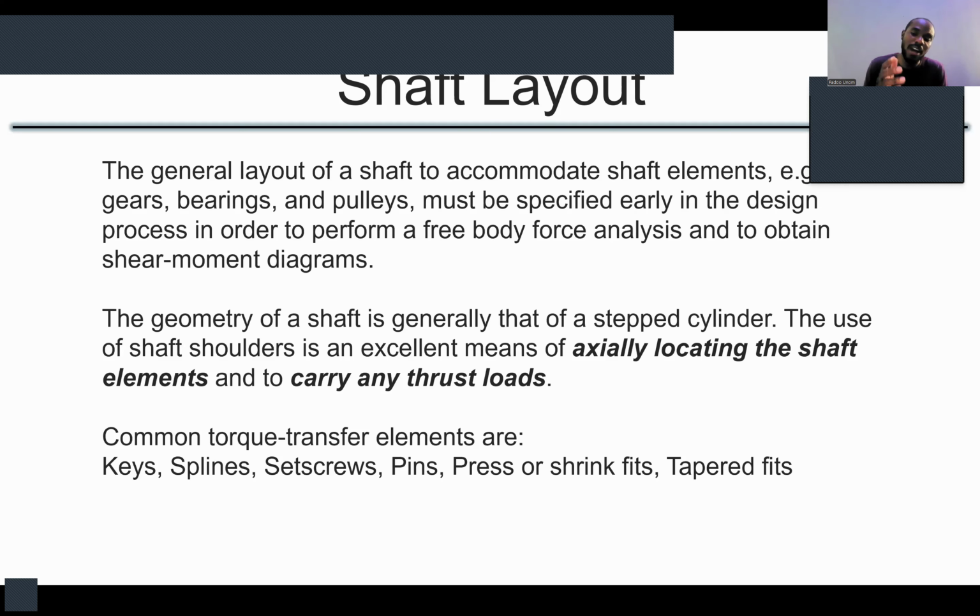Okay, so when you have shaft shoulders, one of their functions is to provide support for thrust loads. So there is something that resists your axial loads. Now remember that if we connect our shaft to a motor, your shaft is turning. It's rotating. The shaft is a rotating member, it's not an axle.